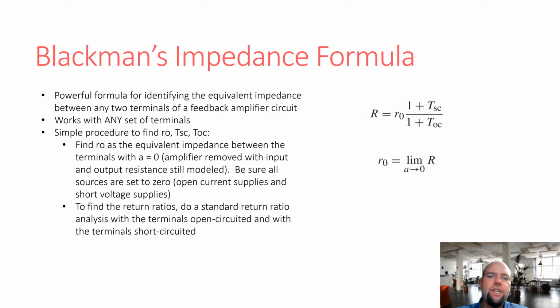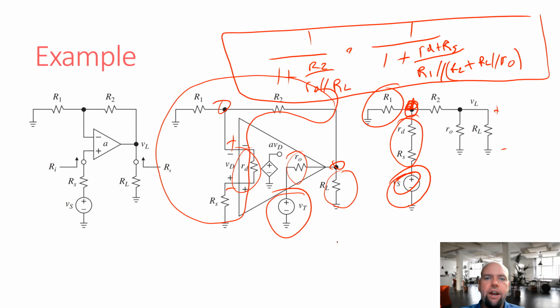This is basically how we'd model an op amp more completely. If we wanted to model an op amp more completely, we could use this return ratio and feed through gain, and we could develop an expression that much better represents the actual closed loop gain of our amplifier than we could using the model that has simply forward gain and feedback gain.